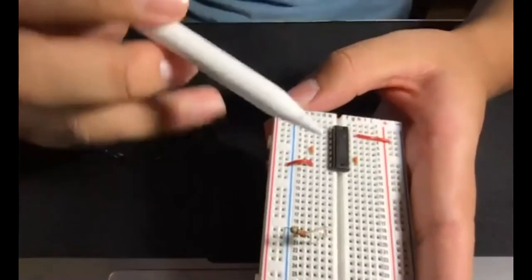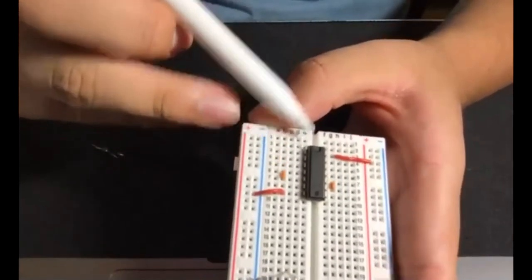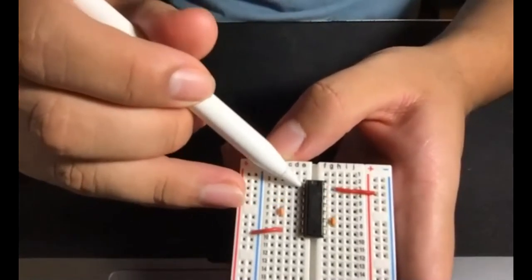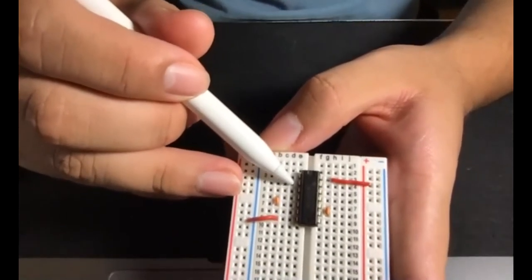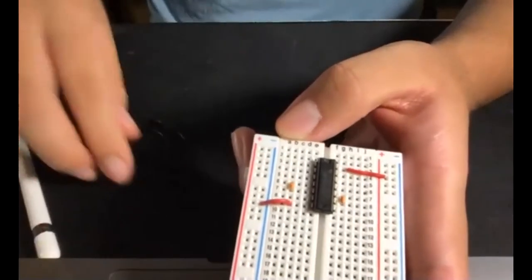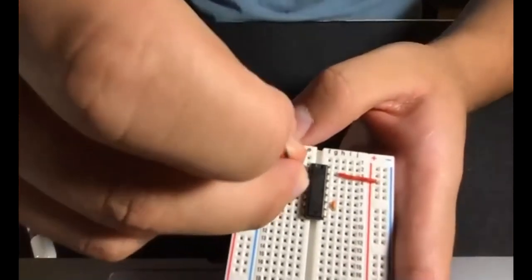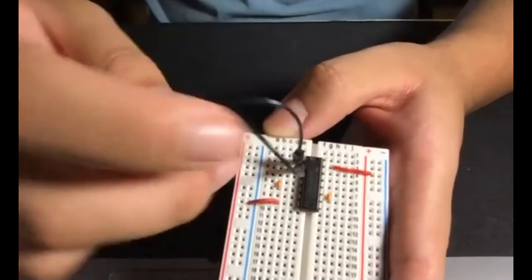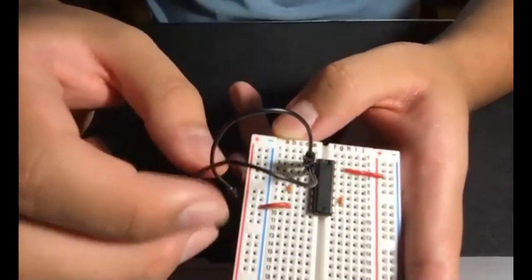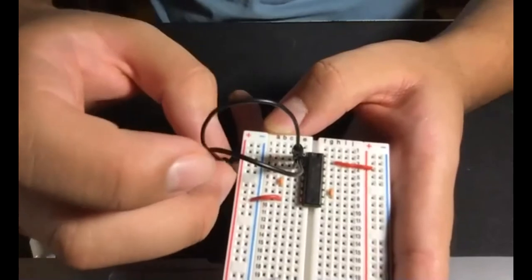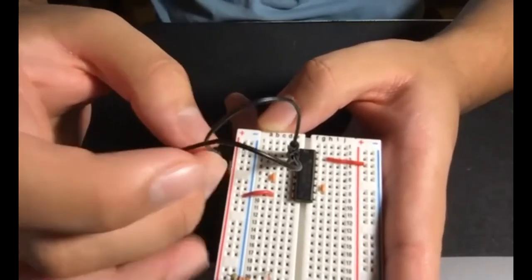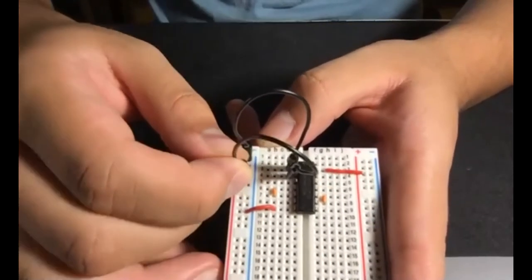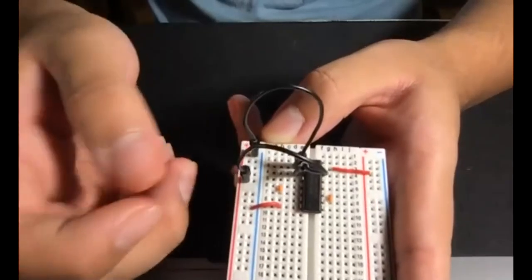I believe the inputs, you would see this in your data sheet, but for this one I have it memorized already. The top two on the left hand side of this specific chip are inputs, and then the third one will be our output. So if we make two connections here, these are going to act as our inputs. And now the thing is, where do we connect these two things? To get highs and lows for your integrated circuit chips, when you go into 201, they're basically zeros and ones. You're either connecting them here to ground, or to your positive, which is your power.